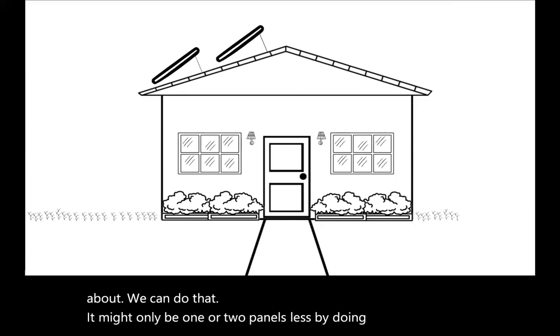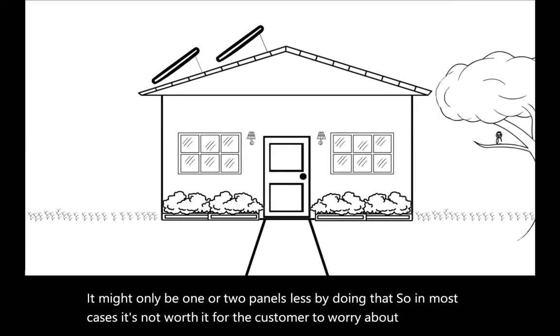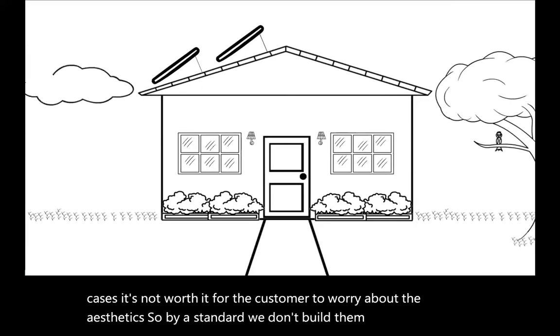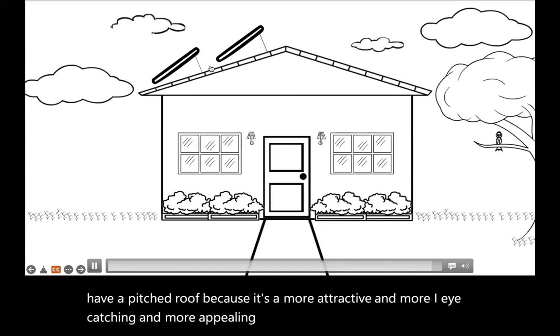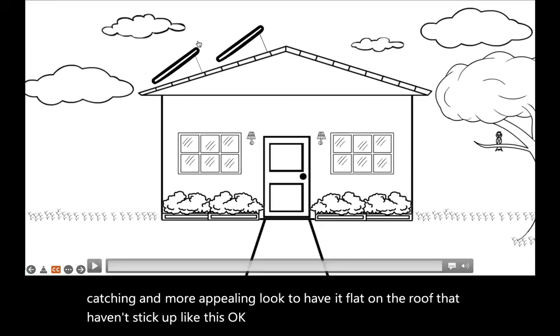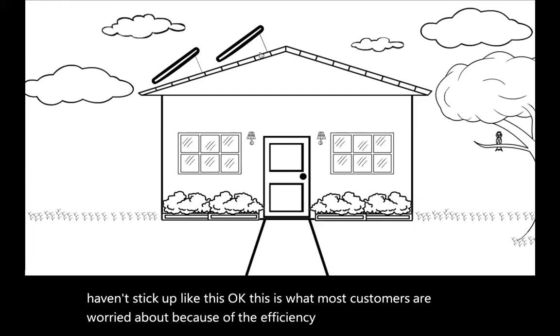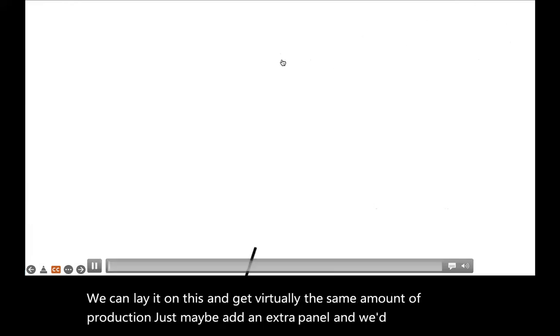So in most cases, it's not worth it for the customer to worry about the aesthetics. By standard, we don't build them like this if they have a pitched roof, because it's a more attractive, eye-catching and appealing look to have it flat on the roof than have it stick up like this. This is what most customers are worried about. Because the efficiency of panels has increased, we can lay it flat and get virtually the same amount of production, just maybe add an extra panel and we'd be just fine. Okay.